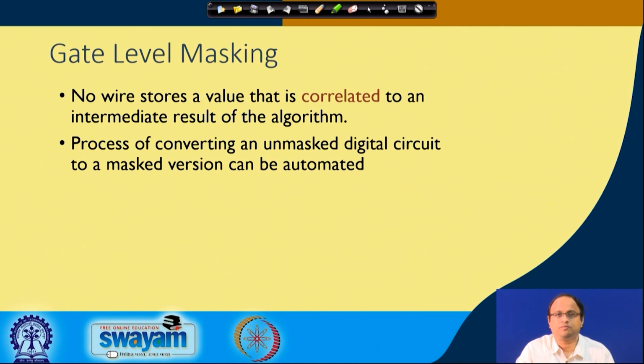So, the idea is that if you are processing data, for example any intermediate value, you would typically try to split it into two parts. One part is the mask, which is essentially hiding your information, and the other part is the masked data, which is essentially nothing but data camouflaged with the mask. We have to process both of them in an independent fashion, and we have to be very careful that no intermediate circuit is combining these two parts, because if we combine the mask along with the masked data, then the unmasked data is essentially exposed. Therefore, we have to do the computation in a manner so that the actual data does not get opened up during the computation.